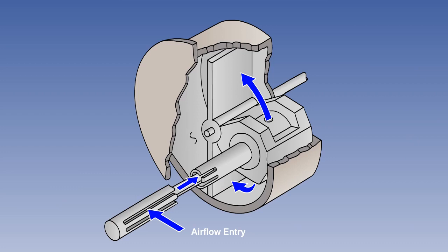The slotted probe sensor consists of a probe with two slots in the surface facing the oncoming airflow, and works on the principle that as the angle of attack varies, the amount of air pressure in the slots will vary also. Air pressure in the probe is transmitted through separate air passages to opposite sides of a paddle in a paddle chamber, as we can see here.